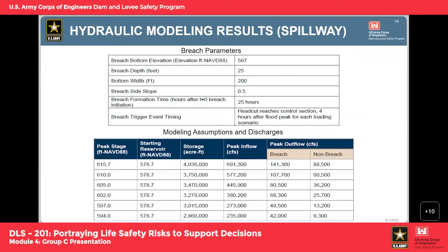Generally speaking, the breach parameters were not varied for the different pools that were considered. The only variable that changed from the different loading conditions was the breach trigger event timing, which was based on when the head cut reaches the control section, and for the analysis was assumed to be 4 hours after the flood peak for each of the loading scenarios. So that time will change from scenario to scenario.